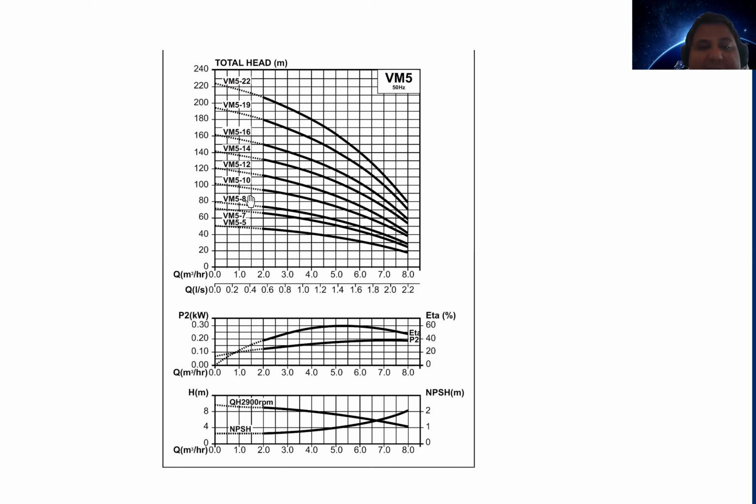A lot of times you can find for a given pump one of two things. You can have a series of curves for the same pump housing with a single impeller at multiple impeller speeds, or you can have a single housing with multiple impeller sizes. The higher the impeller speed and the larger the impeller diameter for a particular pump, the more head that pump can deliver to a fluid, which is what you kind of see here. These are a series of pumps, and depending on the pump chosen and the specifications, the head applied to that fluid can change.